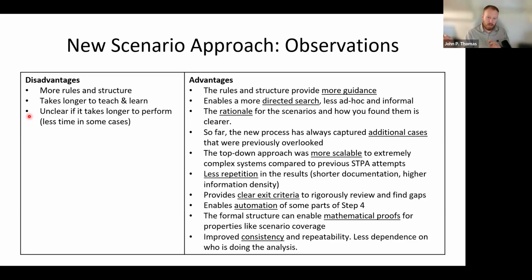Let's try this new process, and I used it because instead of producing 100 different scenarios or 1,000 scenarios, it produces exactly 4 for every UCA. So if you've got 20 UCAs, which is typical, it produces no more than 80 scenarios, which is manageable. It may sound like a large number, but these are massive, massive projects that we're talking about. That is a reasonable number, much better than any other approach I've seen. The same projects would have tens of thousands of failure conditions, functional failure conditions, and failure modes for an FHA or an FMEA. Tens of thousands.